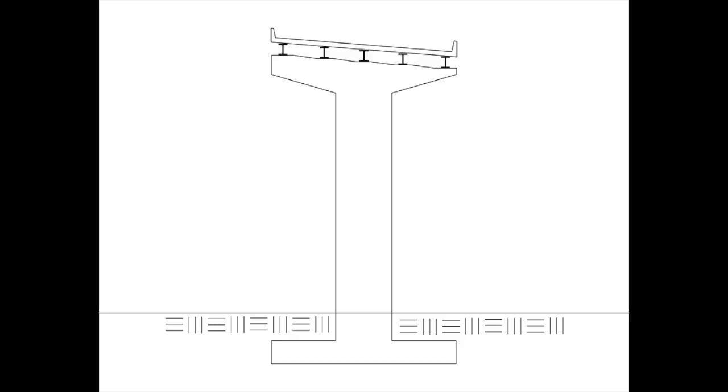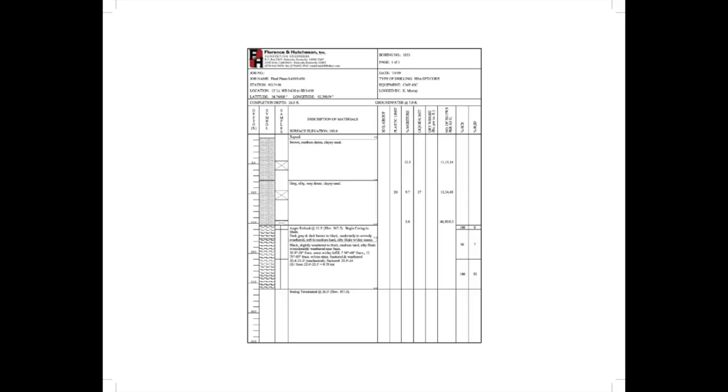This test is common because it is cost efficient, performed in already drilled borings, and a disturbed sample is obtained for further classification. Performance of SPT results in what is known as N values. These N values only represent an index of soil behavior and do not directly measure conventional engineering properties.